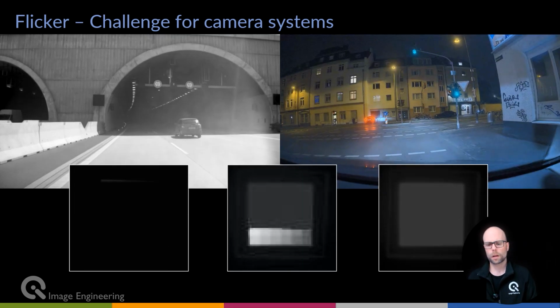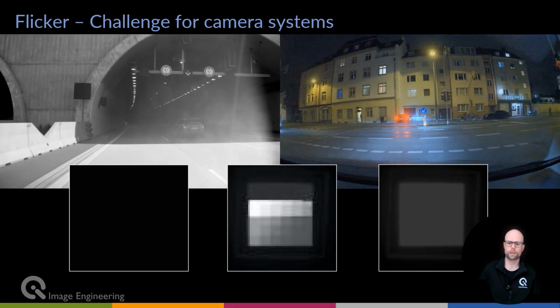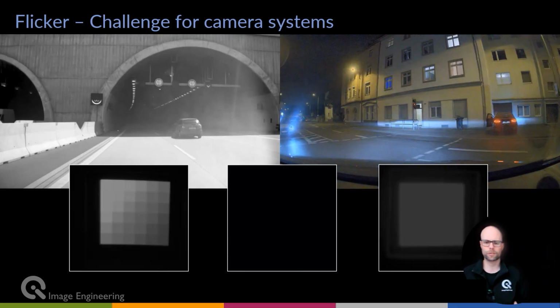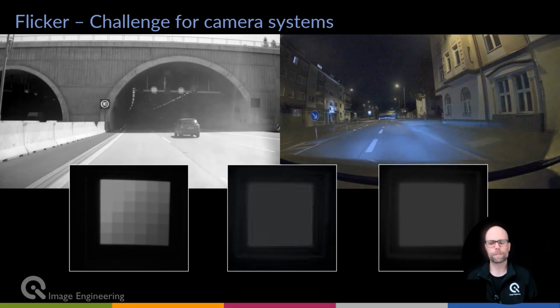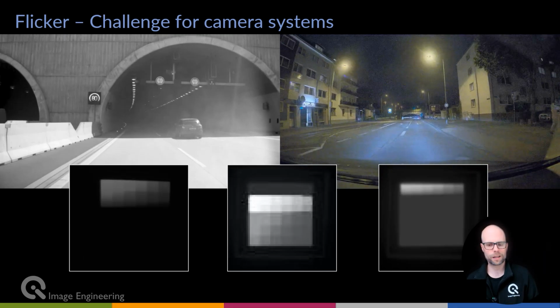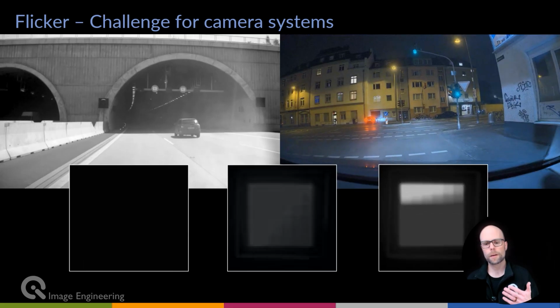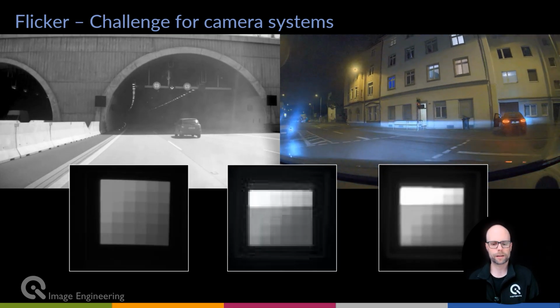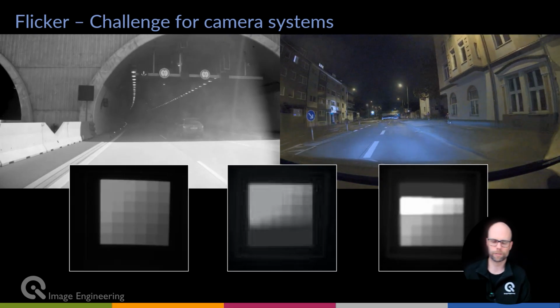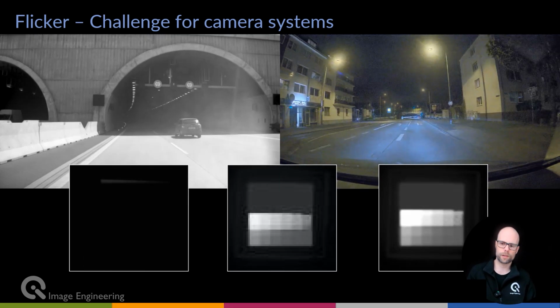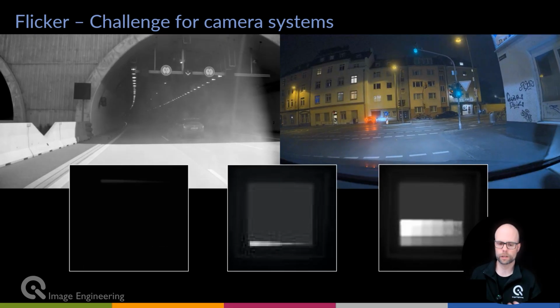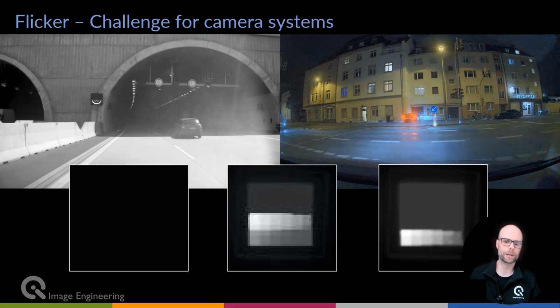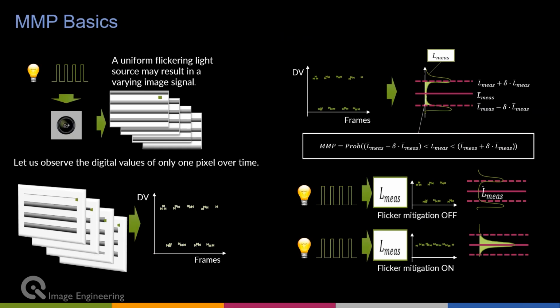You see these videos in the lower part where you have these different artifacts. That is actually the Vega light source creating different frequencies, duty cycles and phases, and that can cause quite different artifacts in the image. So with these light sources you can create these and really check if flicker mitigation in the sensor actually works. In P2020 there is the metric of MMP for that.